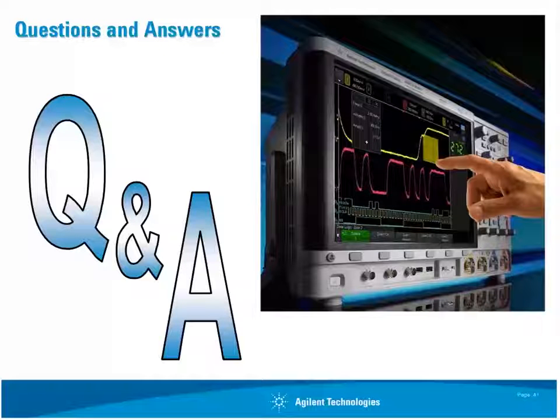Okay, thank you. And a last question, are there any disadvantages of fast waveform update rates? In my opinion, there are no disadvantages. However, we have had some input from our customers. One phenomenon that you will see on a scope that has an extremely fast update rate is some customers say your waveforms look fuzzier, they look more noisy, and they think our scopes have more noise.